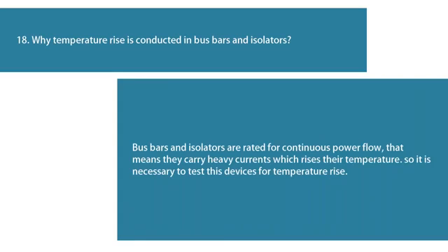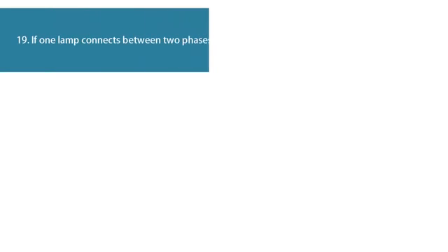18. Why is temperature rise test conducted on bus bars and isolators? Bus bars and isolators are rated for continuous power flow, which means they carry heavy currents which raise their temperature. So it is necessary to test these devices for temperature rise.